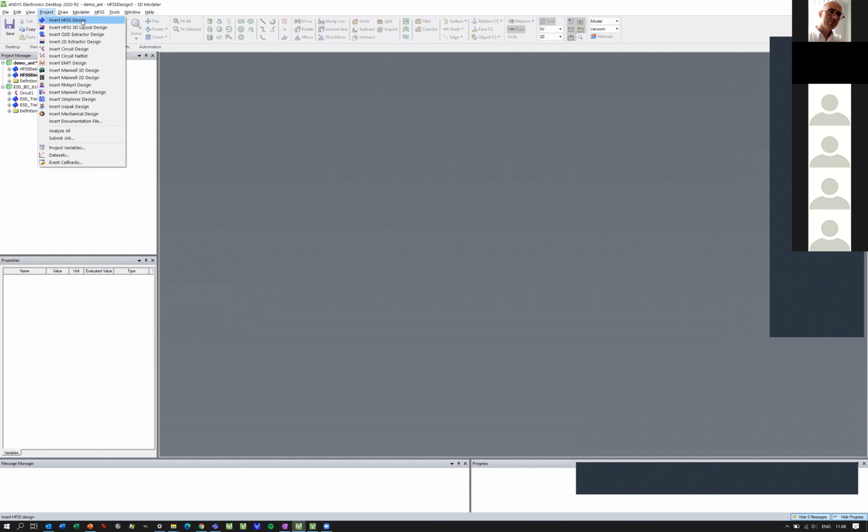That's the high frequency 3D environment. This is actually a circuit board simulator under Electronic Desktop, 3D Layout. Then we have Q3D, which is the RLC extractor, a 2D simplified simulation setup. And this is the SPICE circuit design. It's actually a SPICE environment, like ADS or LTspice or something like that. Then we have low frequency simulations, Maxwell, and a 2D version of that, rotating systems, and we can do the digital twin here too.